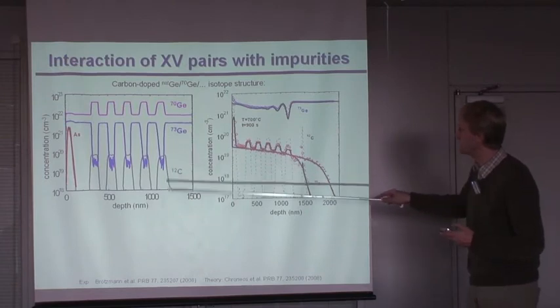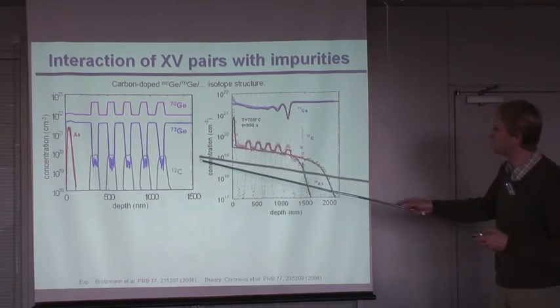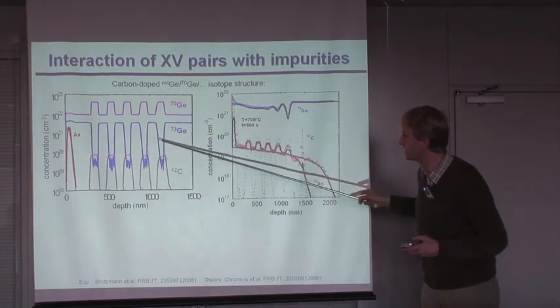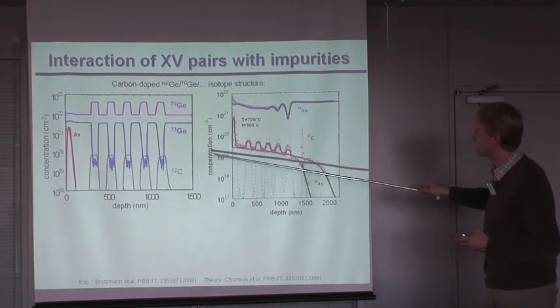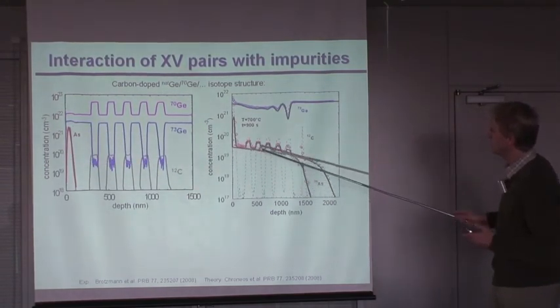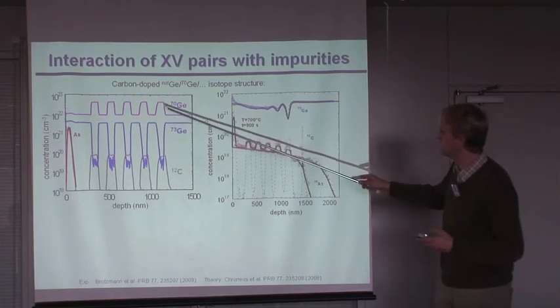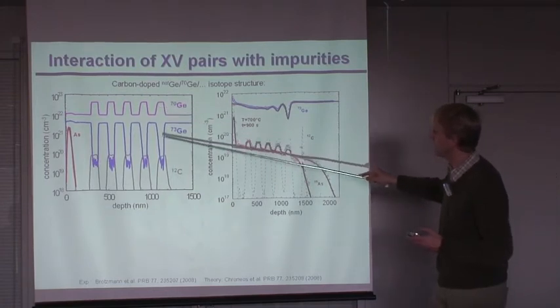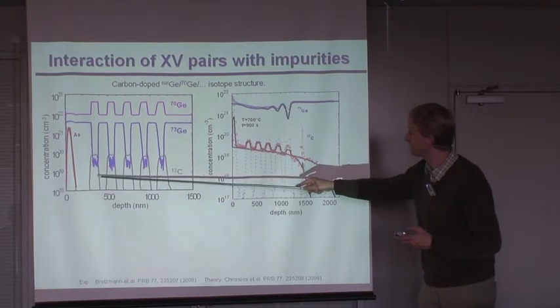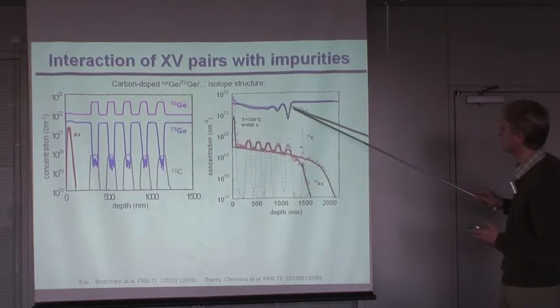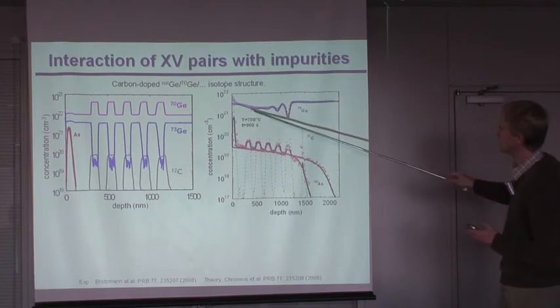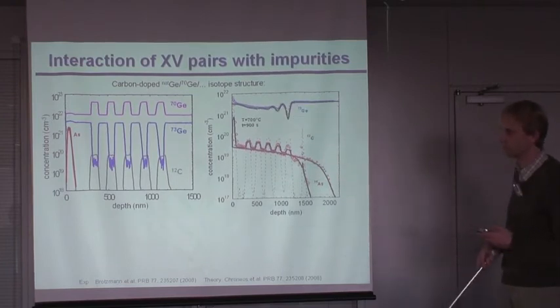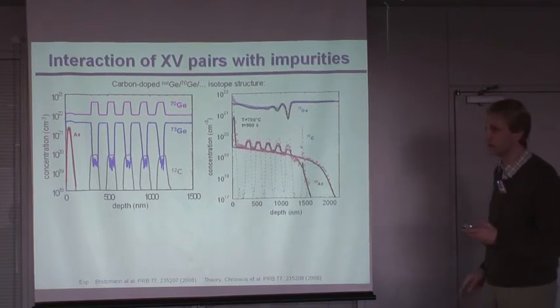And if you have carbon inside, you see what is happening if you then do diffusion of arsenic. Here's the as-grown structure. You have implantation of arsenic, and then you do an annealing step. You see that the arsenic segregates in the area where you have the carbon. The self-diffusion of the germanium is shown here. It's already very, very strong intermixing of the germanium lattice.